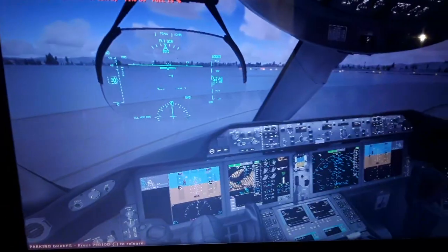Above sea level, we're going to align with the STAR, the standard terminal arrival route, with waypoints and fixes that include horizontal and vertical navigation fixes and altitude and airspeed constraints for the terminal approach and landing of the aircraft. Also, we can be aligned with the ILS localizer, the horizontal localizer, and the vertical glide slope, that receive radio frequency transmissions from antennas with a unique radio frequency. For this one, we're going to be aligned with the magnetic heading of 136 degrees for approach and landing on this runway.